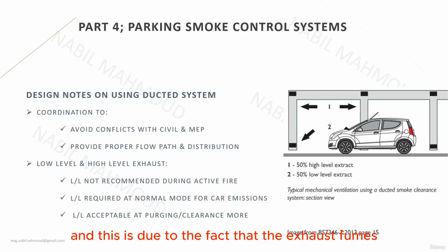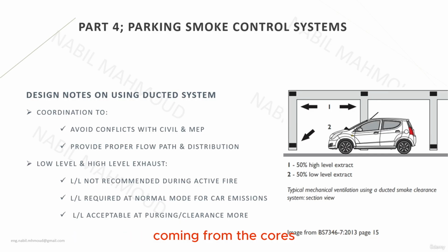And this is due to the fact that the exhaust fumes coming from the cars have a high percentage of toxic gases, and some of these gases have higher density than air, so they accumulate at low level. That's why it is important to provide local extraction points at the parking slots at low level as well as at high level during the normal mode.